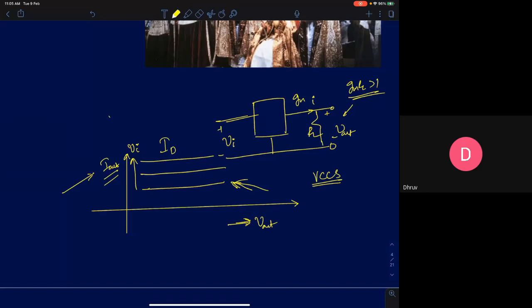In addition to that, you should be drawing little to no current at the input. If you are drawing little to no current from the input, then you will end up having a huge power gain. So that's the whole idea behind all these amplifier structures. And I discussed one very important point about a MOSFET.